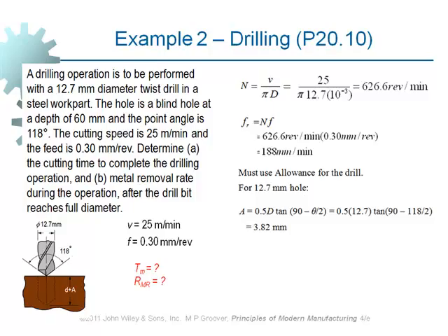Now this amount of A has to be added to the depth of cut, because up to that much, which is 3.82, it is just making the penetration until it reaches the full depth. So it's not considered as the depth of hole. Now this should be added to D, which is D plus A divided by FR.